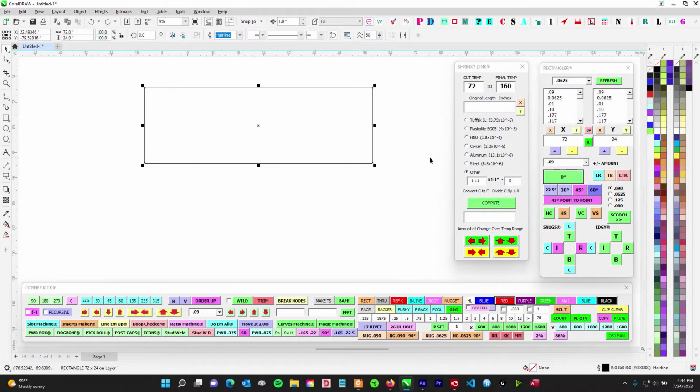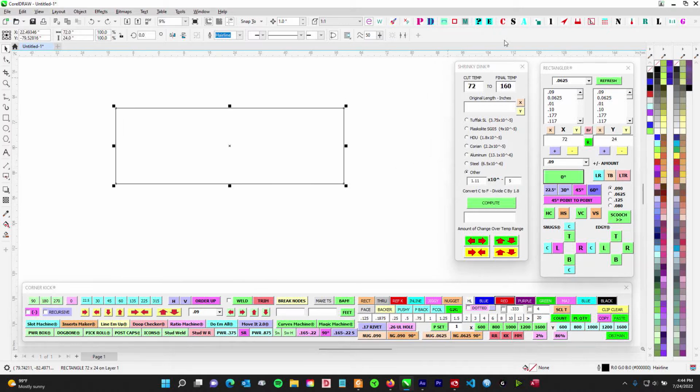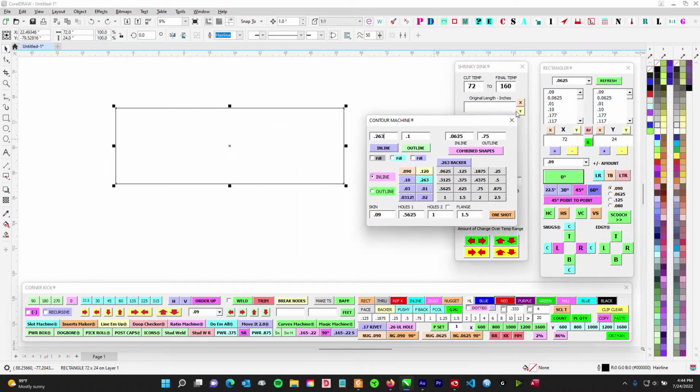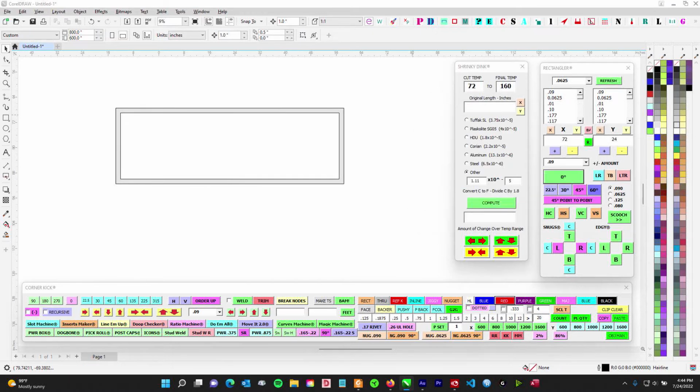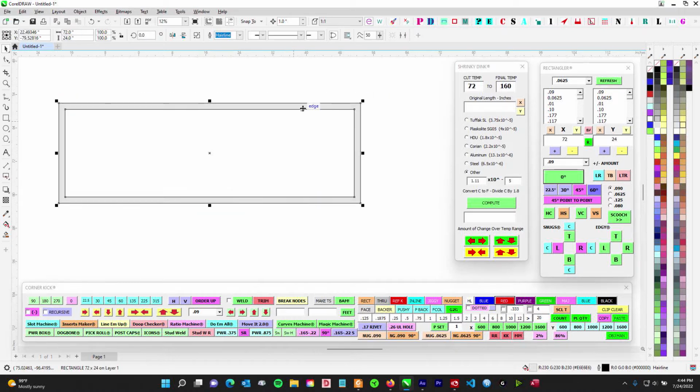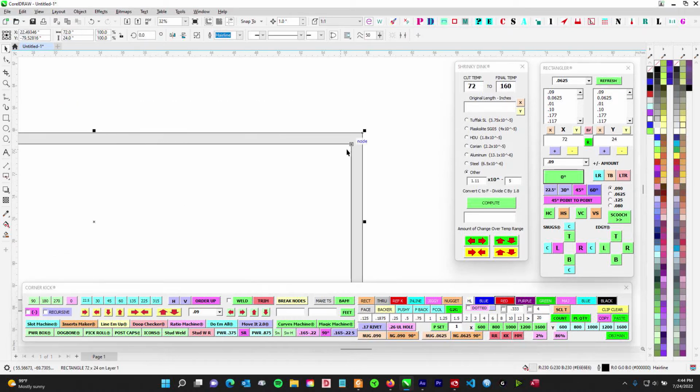So anyway, here's a cabinet. It's 6 foot, and I'm going to go ahead and put a retainer. Let's do a 1.5 inch retainer, and I'm going to combine that. I'm just going to use my 10% for aluminum. So here's my frame. Now I'm going to put retainers on this thing, 1.5 inch retainers, and a slide in face. This is my bread and butter for this thing. It tells me how much to shrink it a little bit so it doesn't push against the retainers.